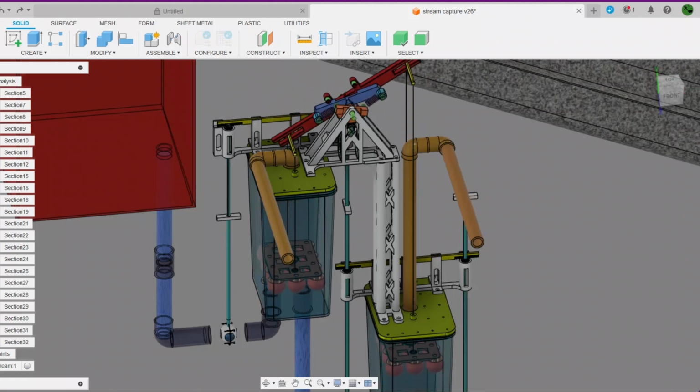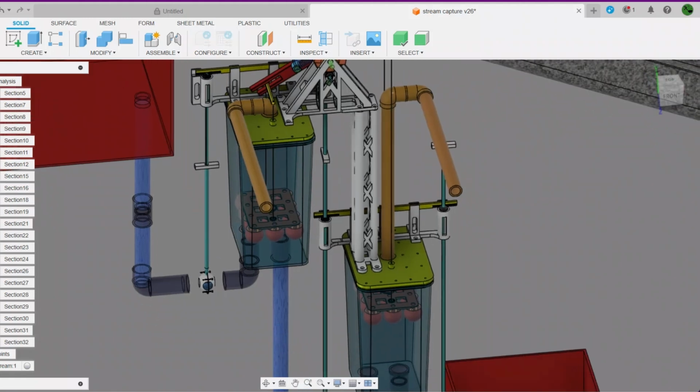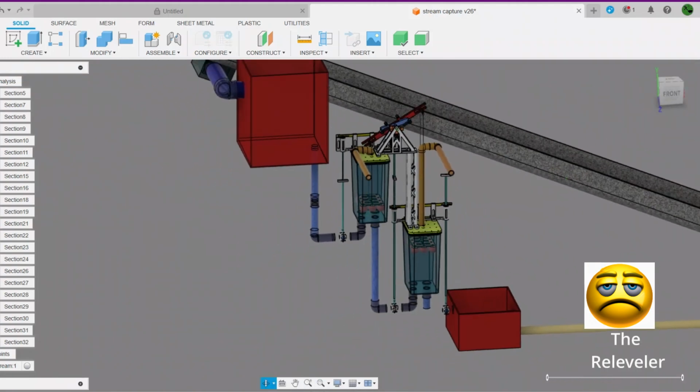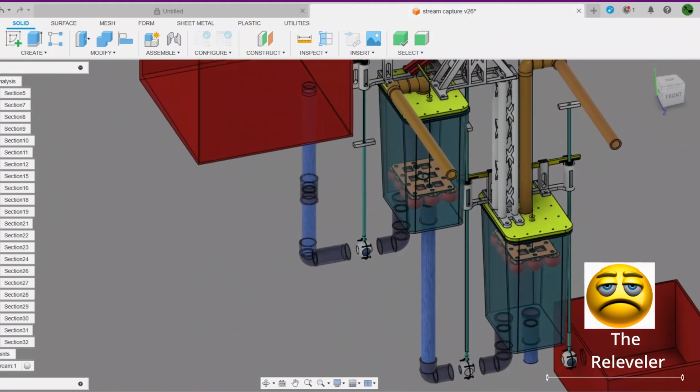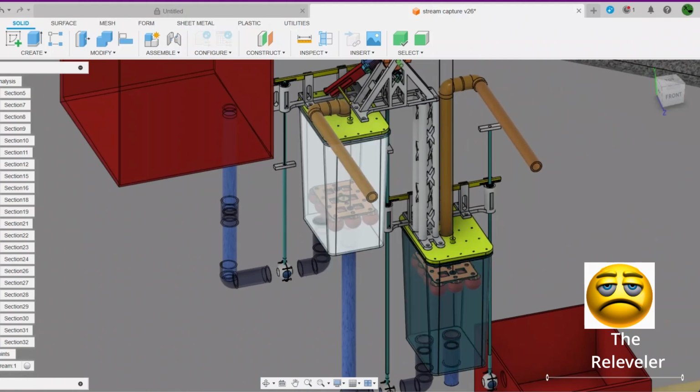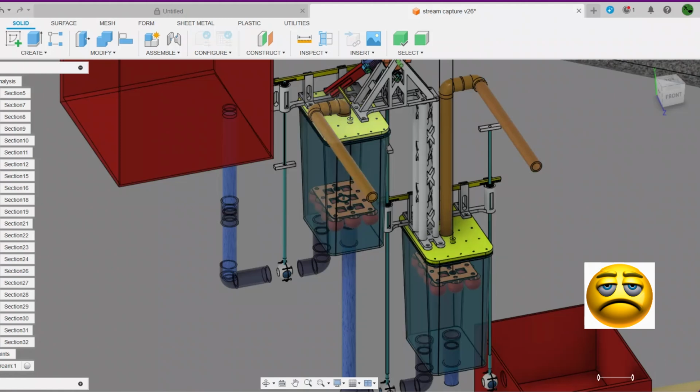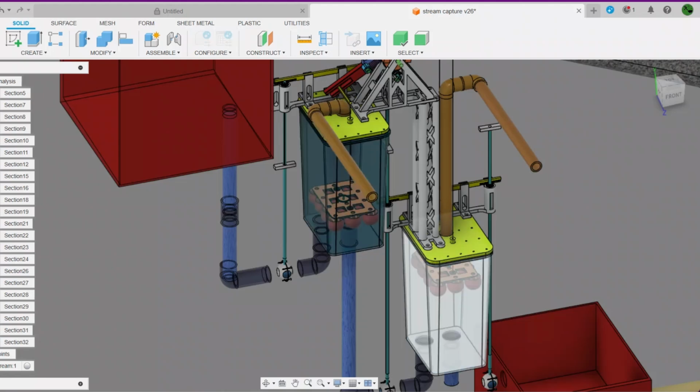So then these just keep changing, and this one's linked to this one, so they're all mechanically linked, and it works. And as water is going in through here, in this one and out this one, as water fills this chamber, the air that was in this chamber gets pushed under pressure and out through this pipe. Meanwhile, this one has the water draining from it, which means that now air needs to flow into here to make up for it because it's a vacuum.